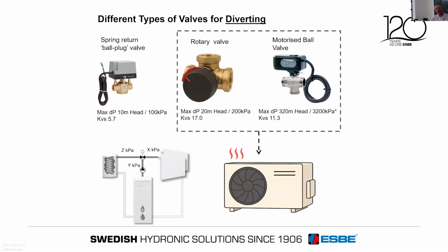So that's why we recommend those 2 valve types for a heat pump installation, because the heat pump's running at a higher flow rate, a higher differential, a high pressure. So a higher differential pressure rated valve and a lower resistance is more suitable for heat pumps. If anyone rings me up and asks which valve should I use, they're the 2 that I offer.